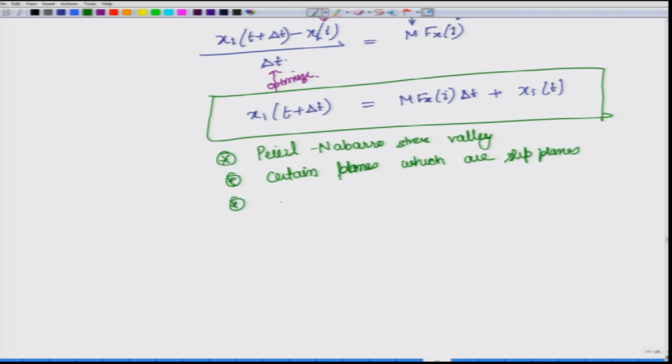You can say that there are mixed dislocations as well as edge and screw, or you can say that only edge dislocation is there. All this will make it more accurate and more complex. You can add image forces that will act on the dislocation, and there are several other parameters that you can add over here. So, for example, the Burgers vector, and so on. This is not an exhaustive list.